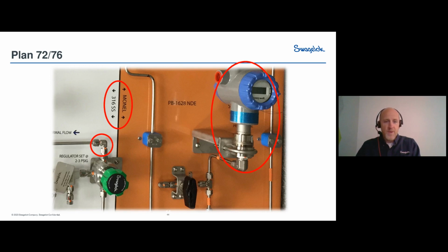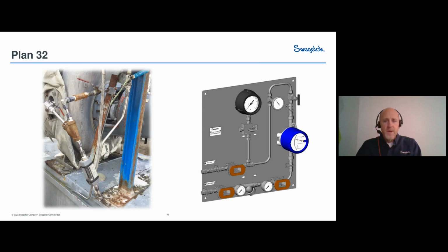That's an area where we were able to improve this system. Got the tube fitting there circled on the left. Those tube fittings actually have little dabs of wax on them, so we can see if they've been tampered with, if somebody has loosened them. And look just to the left of the pressure regulator there. In this case, we've got a vinyl wrap on the panel where everything's labeled. We've actually got the regulator set point labeled on there as well. So a lot of information on the panel itself makes it really intuitive for the operator who's interfacing with this system.